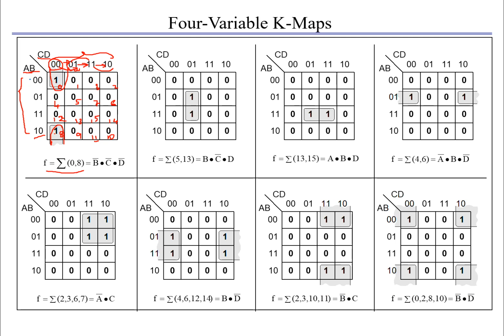If you see here about A, we'll start from A. Here A is varying from 0 and 1, hence during simplification it turns to 1, hence A is not necessary to consider. If you consider B, your B is maintaining a value of 0, hence we are writing B bar.